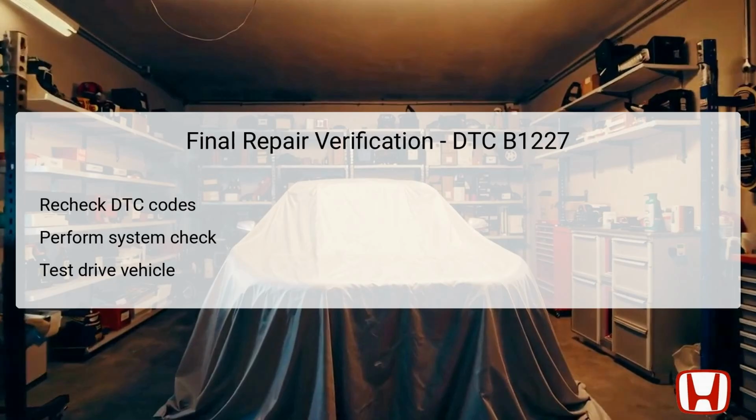Following the DTC check, it's important to perform a comprehensive system check to ensure that the climate control functions correctly and the outside air temperature readings are accurate. Finally, take the vehicle for a test drive, ensuring that all aspects of the climate control system respond appropriately to changes in temperature settings and external conditions. This final step helps to confirm that the repairs made are effective.